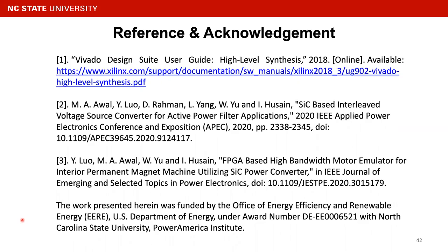Do you expect commercial off-the-shelf HIL simulation platforms like Typhoon or dSPACE to be able to do similar tasks to what you did in the motor emulator? Our motor emulator is a power hardware-in-the-loop setup, but some of Typhoon's products are signal-level hardware-in-the-loop, so we can actually provide more realistic results by using our setup here.